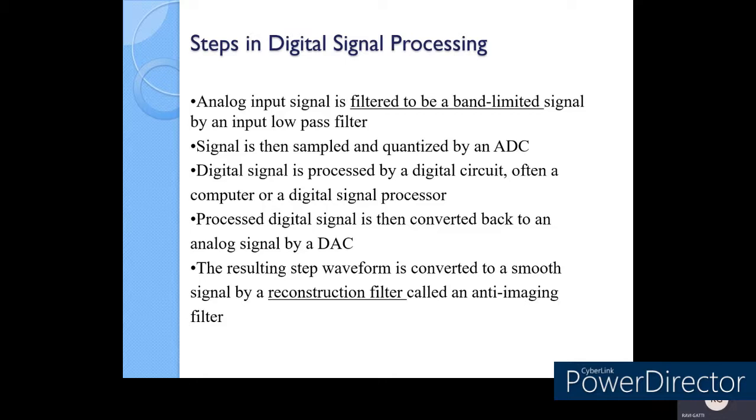In sampling there are several sample values, and these sample values have to be quantized, or minimized. In order to minimize these sample values, or discrete values, we go for quantization. This quantization is the second step in the conversion of analog values into digital values. After quantization, next we go for the coding. For each quantized value, we assign binary values, and this assignment of binary values to the quantization levels we call the coding mechanism. These are some of the techniques we use in the conversion of analog signals into digital signals.